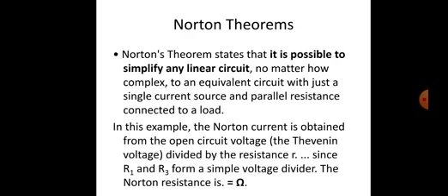Formula for Norton's theorem: IL equals ISC times RTH divided by RTH plus RL. Norton's theorem is used to find the equivalent and simple circuit of a complex electrical circuit. In this, the various circuit resistances are replaced by an equivalent resistance and a single current source.